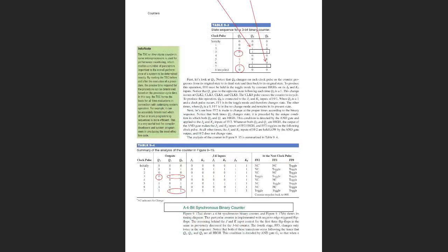Okay, so why is it so? We have to take a look at this situation. We have 3 binary flip-flops counting from 000 to 111, and you may see that when clock 3 comes, Q0 and Q1 are both 1. At clock 3 we need to change Q2. So if Q0 and Q1 are 1, we toggle Q2 for the first time from 0 to 1.